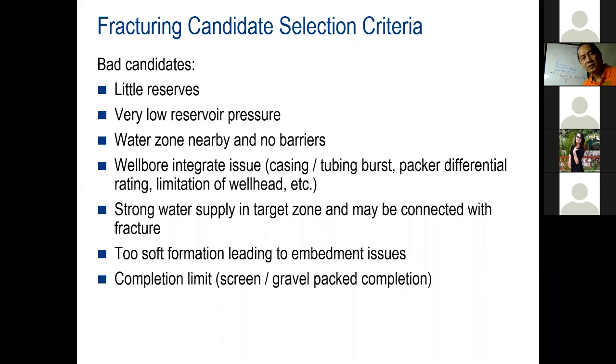The point is, yes, you will put in artificial lift, but your penetration is deeper into the reservoir. You are pumping a frac fluid, which is a damage to some extent, right? If you don't have a good reservoir pressure to bring all this damage from the frac fluid back to the wellbore, even though you put artificial lift at the wellbore, you will not have a good fracturing job. And how low is low reservoir pressure?